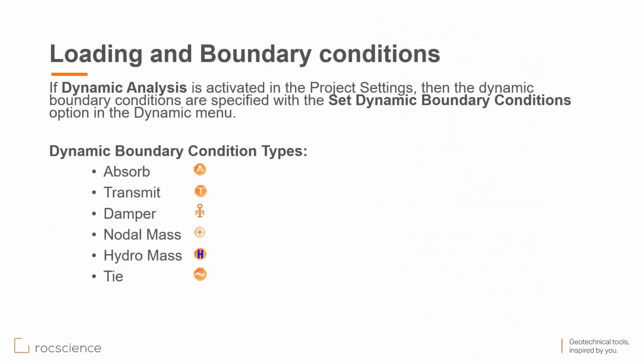We also provide a lot of loading and boundary conditions for dynamic analysis. For example, you can have absorb, transmit, damper, nodal mass, hydromass, and time boundary conditions. So with all of the boundary condition types here, you can create models to simulate most of the real life problems.